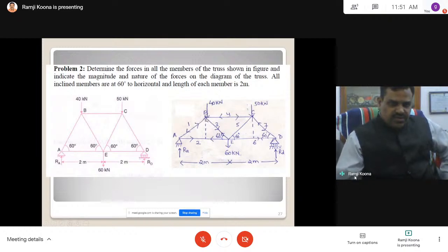Now let us go to this joint. First let us go to E. When you go to E, this is known because of equal and opposite. Whatever is there, you have to apply in the opposite direction because this is already fixed in magnitude and direction. That's why, as per Newton's third law, equal and opposite internal force. So from this point, this is known to you, this is unknown.